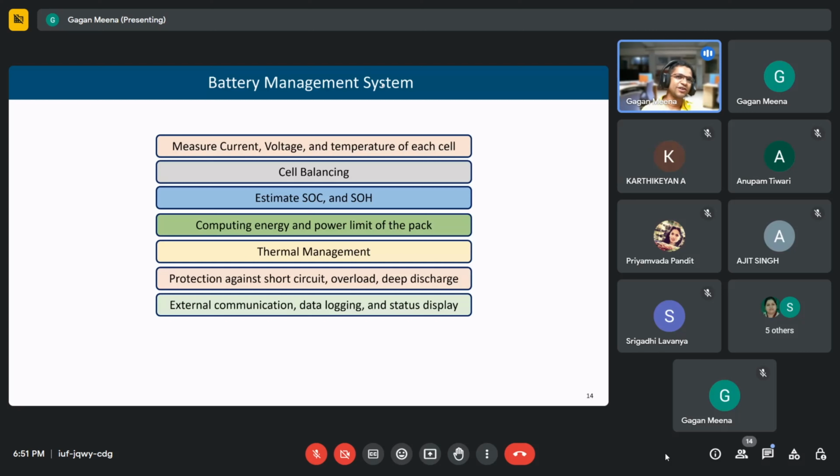So to reduce the costs, what they will do is invest less in the battery management system associated with the battery. The thermal management system is not that good. It is of poor quality, and because of that it is not able to contain the temperature of the battery, and then the battery simply explodes. It's very important for a lithium-ion battery. Not just battery, for any inverter or converter also, the cooling system has to be very good. Especially for lithium-ion batteries, the thermal management system should be very good. The main reason for all these vehicles catching fire is this poorly designed thermal management system, because they want to reduce the cost.